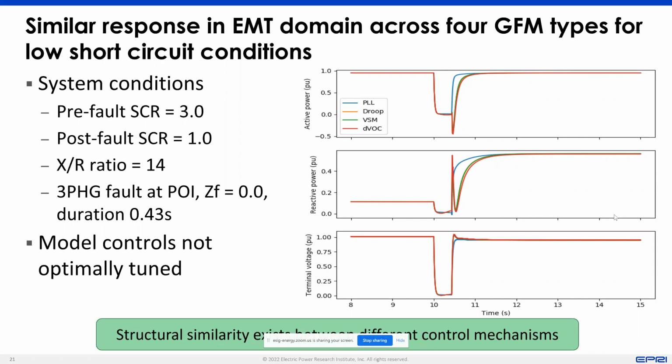If we look at it from the principle that at the end of the day, what they're doing is fast voltage control and fast frequency control at the inverter level, and we start applying those principles in, let's say, our interconnection requirements or in characterizing what should be grid forming, then we can allow for many different types of control to be developed by manufacturers without putting down restrictions on specific control elements to be applied.